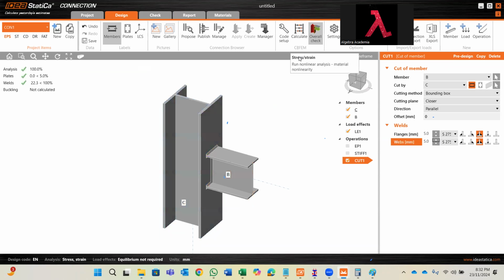Fantastic. It doesn't have any concerns of the bolt at all because I've already removed the bolt. So it will have only the concerns of the weld. Whatsoever forces we have mentioned, those forces have to be catered by the weld thickness. But you know something, when we saw the manual calculation, I already told you the weld capacity is much higher than the bolted capacity, right?